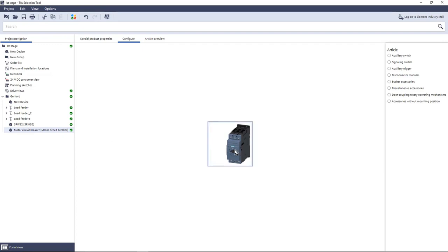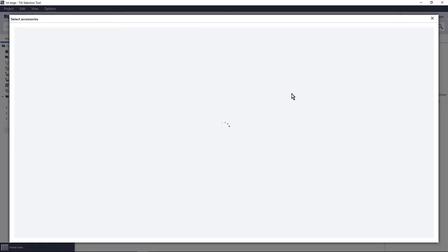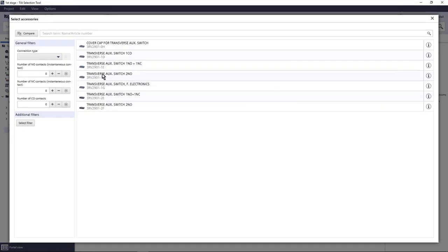And we have a short circuit breaking capacity. As for now, we keep it as a standard 65 kiloamps. Okay, as you can see here, you can also add up instantaneous contacts. As for now, we will keep just the circuit breaker. You double click on it and automatically it's again added here into your project.